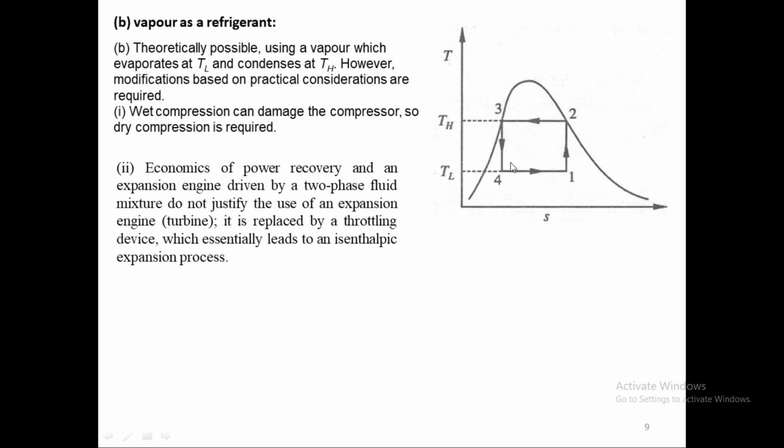And the other one is when the condenser probably is okay, when it can condense saturated vapor to saturated liquid, but when the saturated liquid is expanded into the evaporator, during this expansion process we can think of why not place some kind of expansion device that can extract some work out of it, like you have in the steam engine.